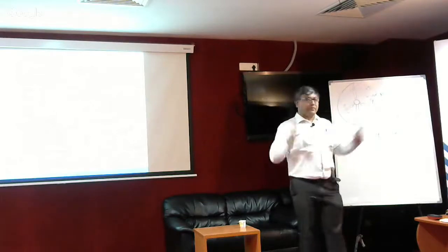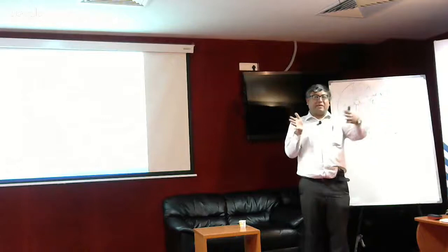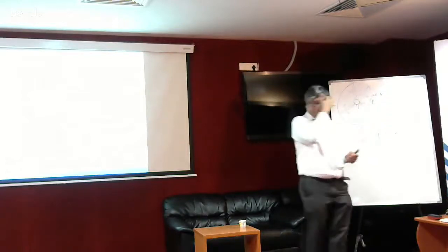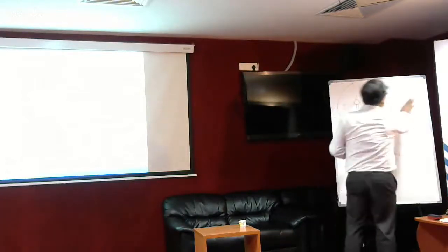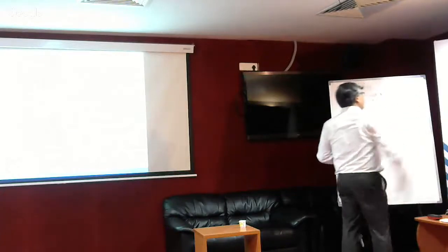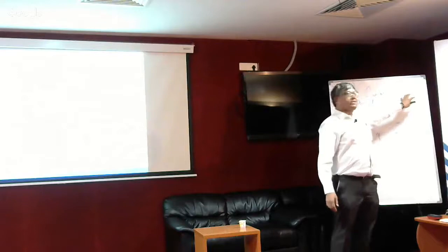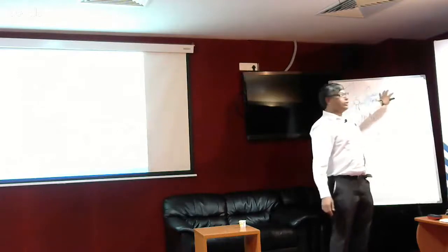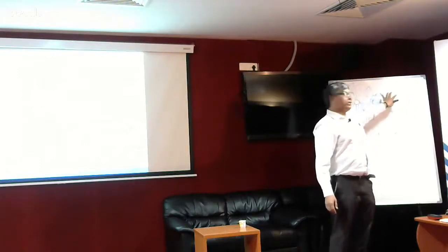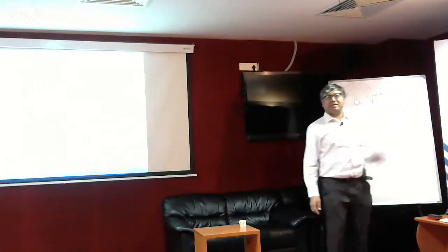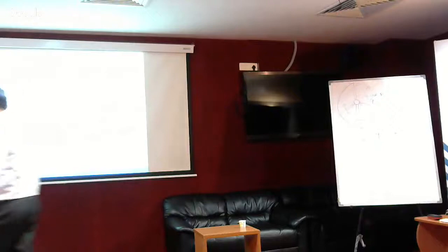When the big ones break down and cascade to smaller ones, energy is transferred from low to high frequencies, and then at higher frequencies it dissipates. This is where the viscous terms dominate. This is where the inertial terms dominate. So this is the inertial range, this is the viscous range. This is how the dissipation takes place, and this is exactly what we're doing.